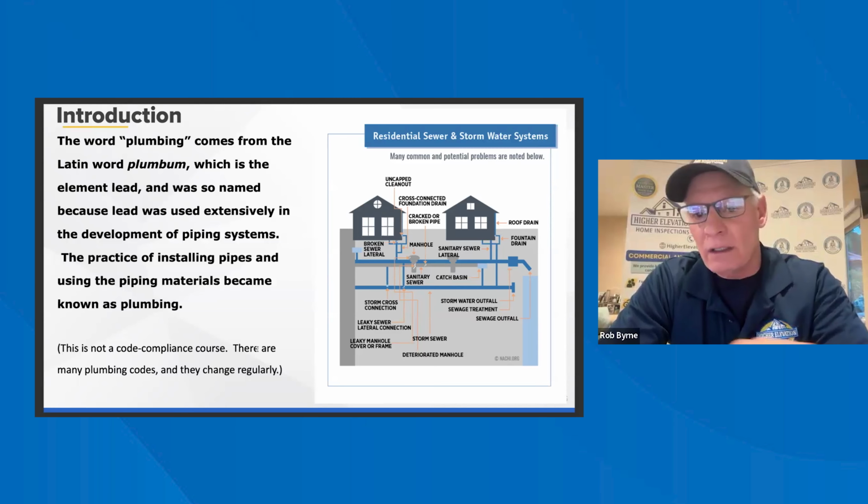So we don't have any leaks there. Now we'll come over to this side and check it. Make sure our slope is correct. Make sure we have one P-trap, not two. We're going to reach your hand up, make sure that we have a clamp on our disposal wire. Looking at the plumbing here, they could have put a high loop or a standpipe on the dishwasher because it is set up for one.